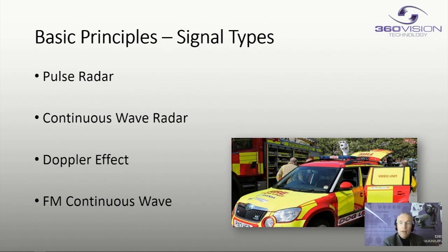So a waveform is being sent out by the radar. If it hits a target which is moving, the reflection will modify that waveform, and we can detect the modifications in that waveform to estimate whether a target is moving towards or away, and potentially how fast it is moving as well. This can be further mixed in with frequency modulation continuous wave.